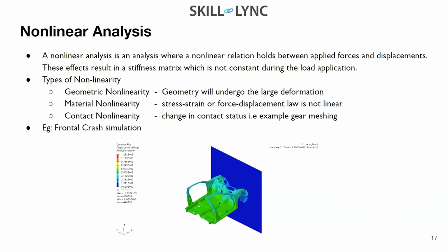So indirectly, from the basic outcome of the problem, you can understand that everything here is time dependent. Like you can see in this animation, the stresses, strains and everything developed are dependent upon time. And why non-linear? Because there is a sudden deformation in a very small amount of time. Also, a car is not made up of one material; different materials are applied to different components, and you are studying the entire BIW collectively. By BIW, I mean body in white, the outer structure of your automotive.